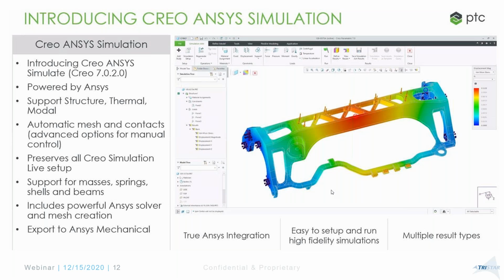When you get into larger assemblies and complex geometry, some of you may be aware of idealizations in FEA. Idealizations are mathematical approximations. I might have a huge engine or a huge assembly that sits on a mount frame, and I'm interested in the frame, not really in analyzing the huge assembly. I can mimic that as a data point, and maybe set it as a mass element. Or if I have sheet metal parts or thin geometry like ribs, I might do that as a shell idealization. So it's computationally less expensive, and that's the whole goal.